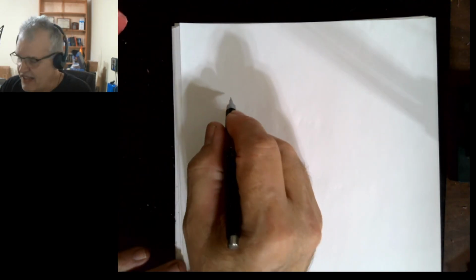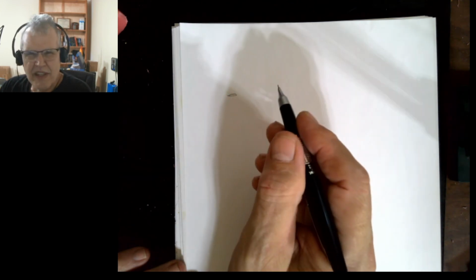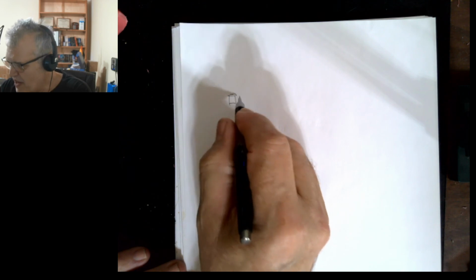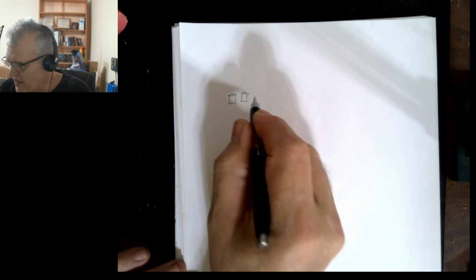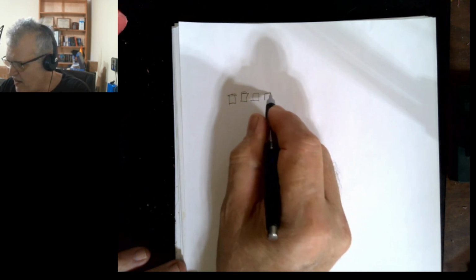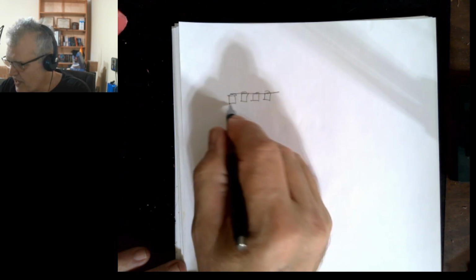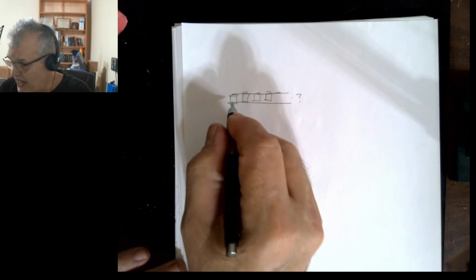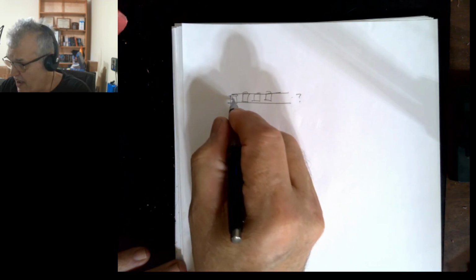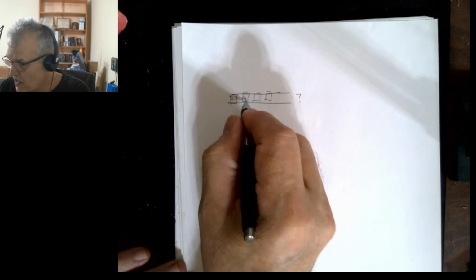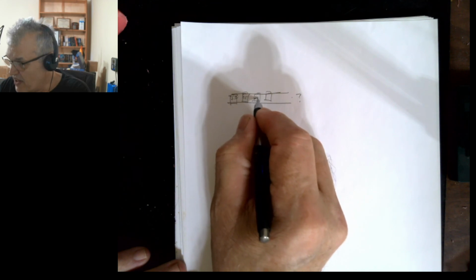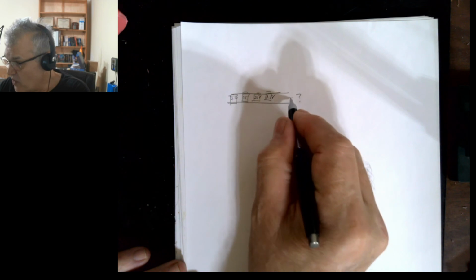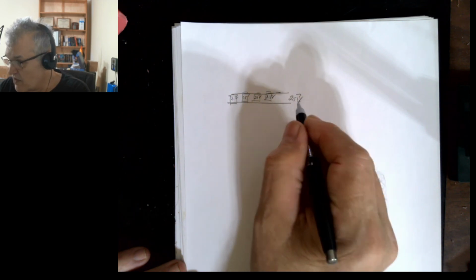So if I take a set of cells, and I hook them up so that all of the positive ends are hooked together and all the negative ends are hooked together like that, what is my voltage out here? Well, if these are all 2.5 volts, then it's easy to see they're all going to be the same voltage since they're all hooked together. This is going to be 2.5 volts.